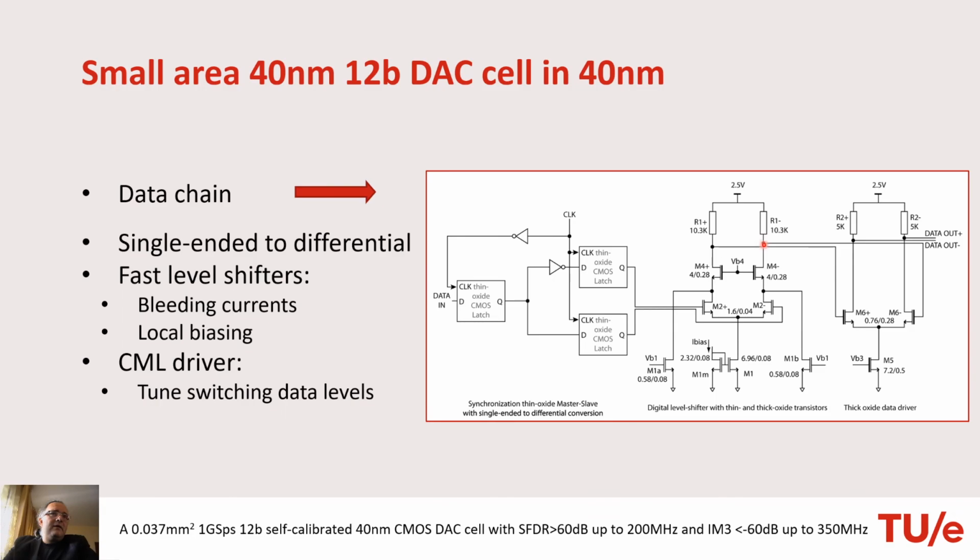Then this is fed to a CML driver, which will adjust the levels of the signal to be good for the current switches in the DA cell. So all these transistors are thick oxide and these are thin oxide.